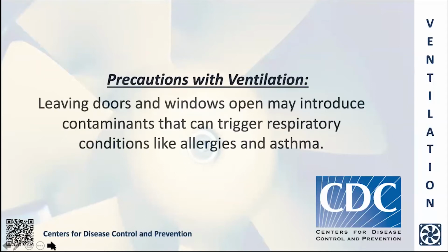And there are also safety concerns associated with leaving doors and windows open. So while this may be the easiest way to ventilate a conditioned space, the safest way is to do it with fresh air ventilation systems that are incorporated into the heating and air conditioning system of that occupied environment.